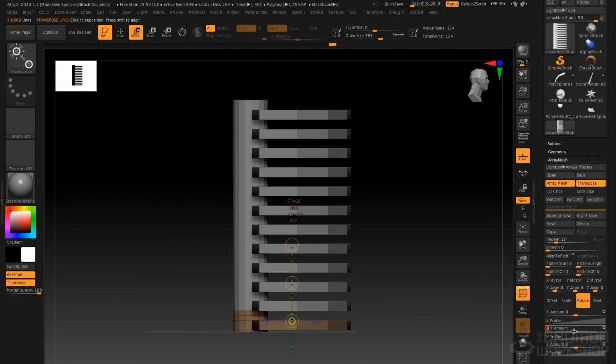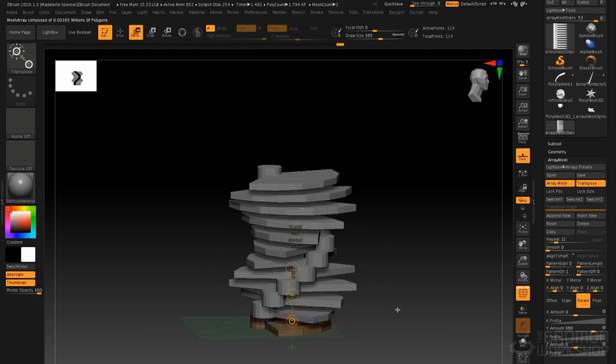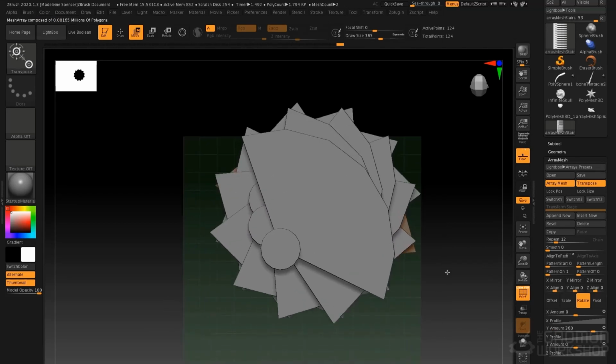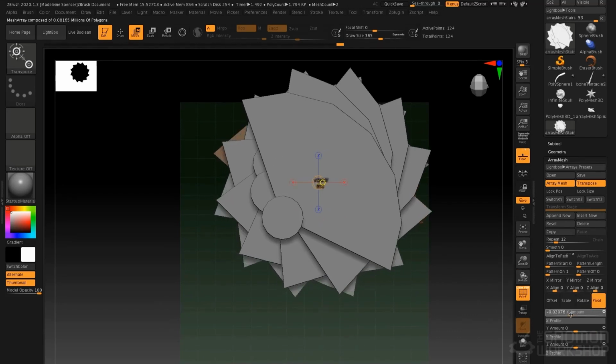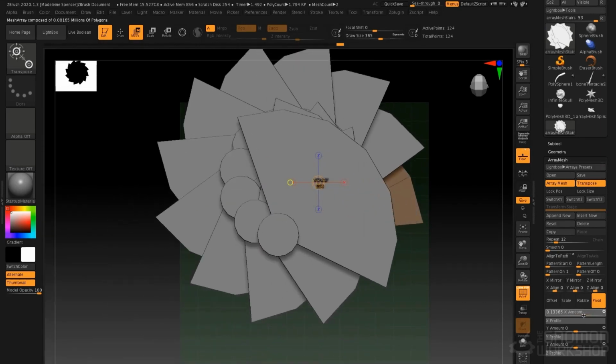We'll go to the Y amount and rotate it around 360 degrees. And now you see it's starting to rotate, but it's not rotating around that central pillar. So I'll snap to a top view and we'll change the pivot. So now I can adjust the pivot. If I click and drag, it will snap the pivot to degrees, or to units, I should say.